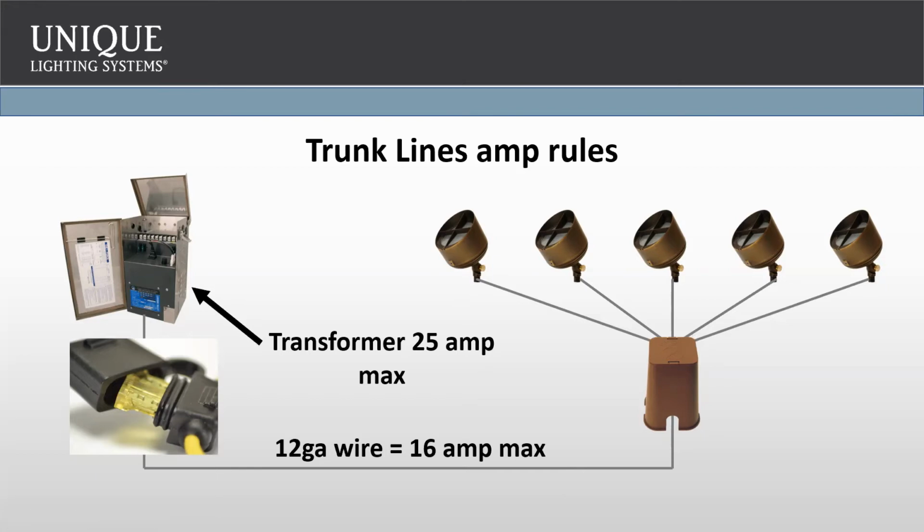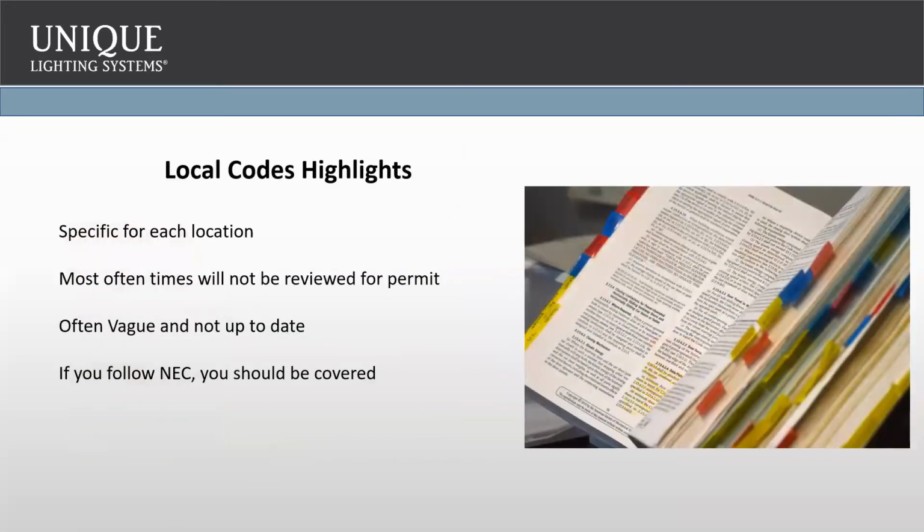It's a lot to think about. It's a lot to remember. Usually you can cover it with a note in your general notes rather than trying to go through all your plans and figuring out what size to put on there. If you put a note that, hey, there should be a fuse coming out of the transformer and that fuse should be sized per the load, that would cover you, and contractors should be able to follow that as you go through.